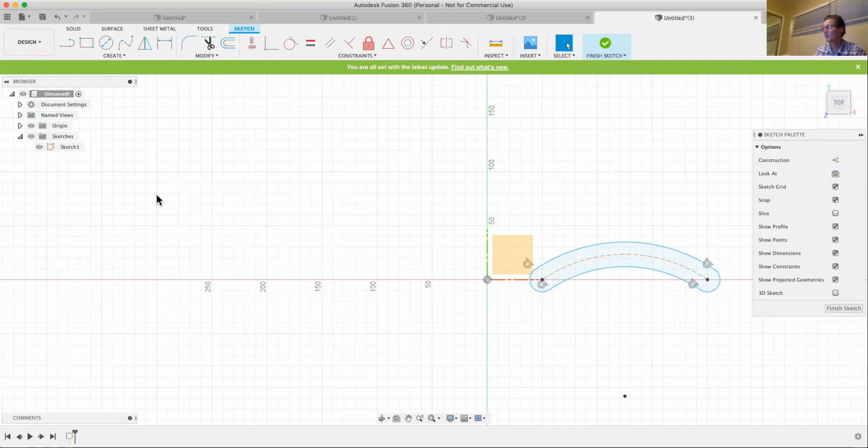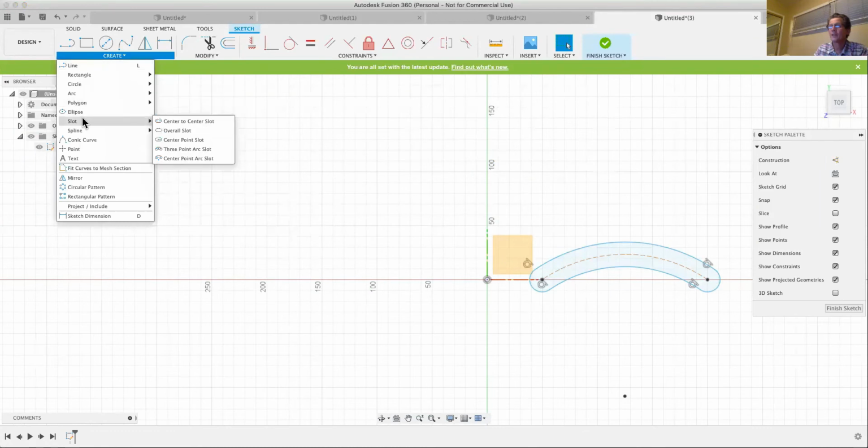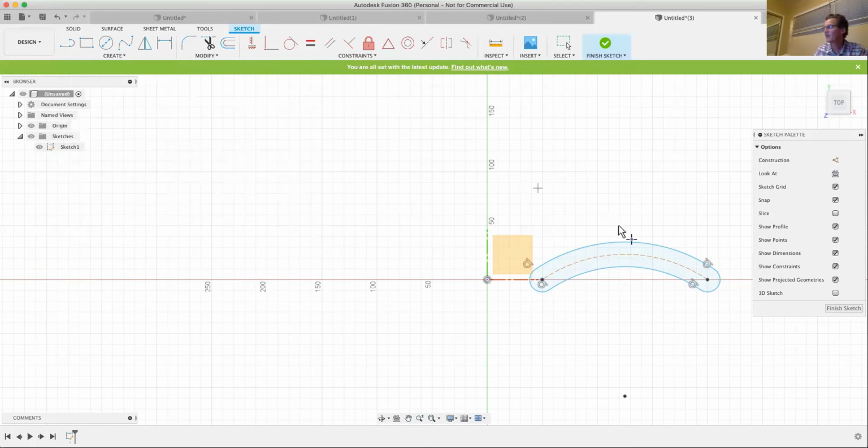And while I'm here, I'm just going to show you a couple things. So I'm going to jump past a couple here and go to point, sketch point. So sketch point is kind of like one of those datum things. I'm going to put this sketch point right at this midpoint. And the sketch point is a point you can define in your sketch to use again elsewhere.